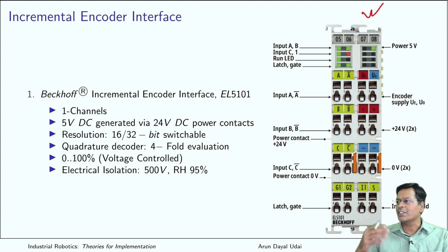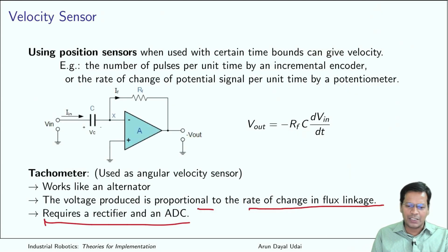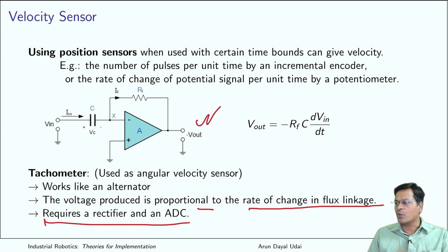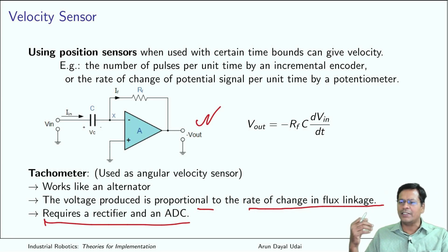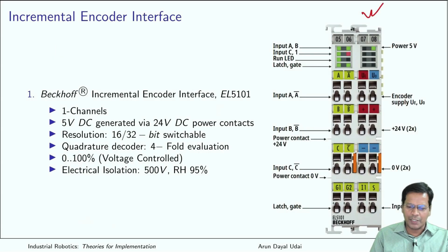Okay, so in industry you need reliability which is at its peak. So there are a few methods of doing it. Maybe if I am able to acquire this voltage signal, in my own software I can take a software derivative also. I can differentiate things in software. You can directly take in the pulses from your standard digital input channel and just count the number of pulses, and you will get the velocity. These are a few ways, but yes, in industry there are dedicated ways of doing it.